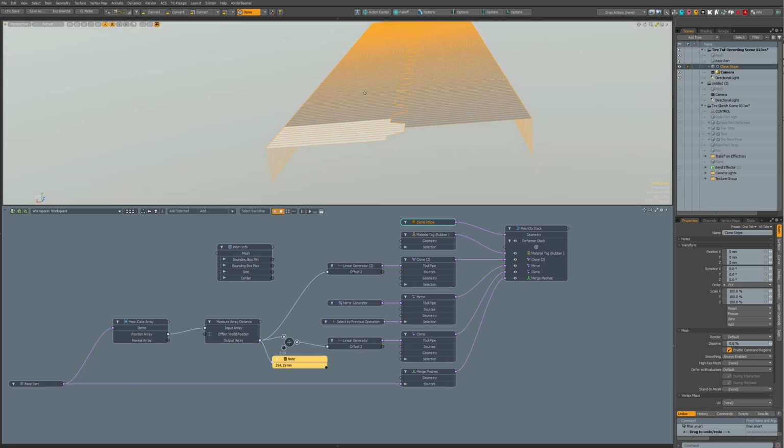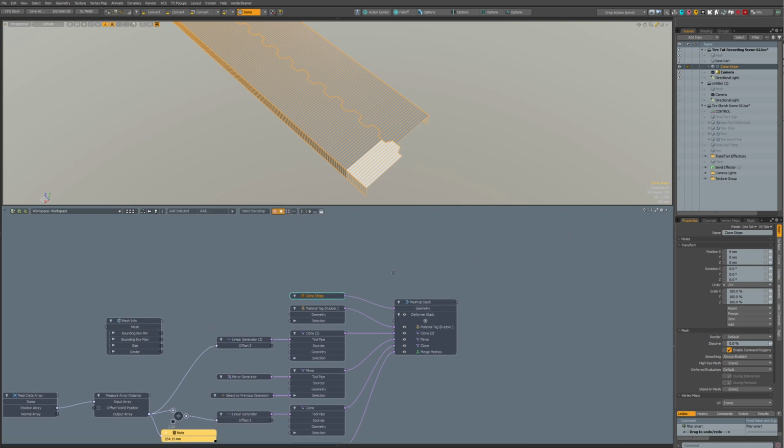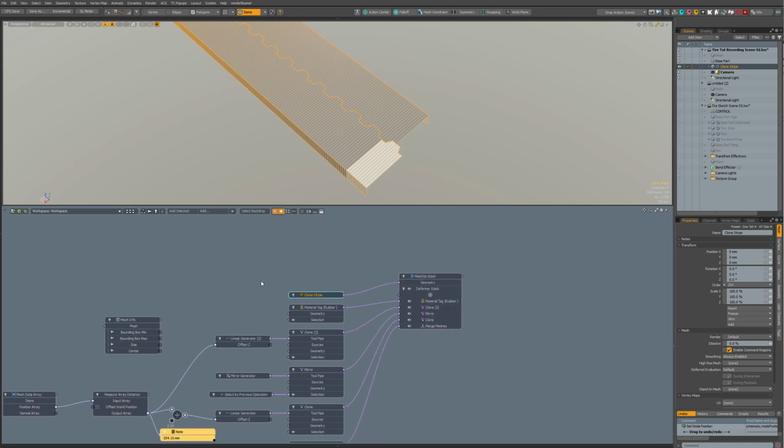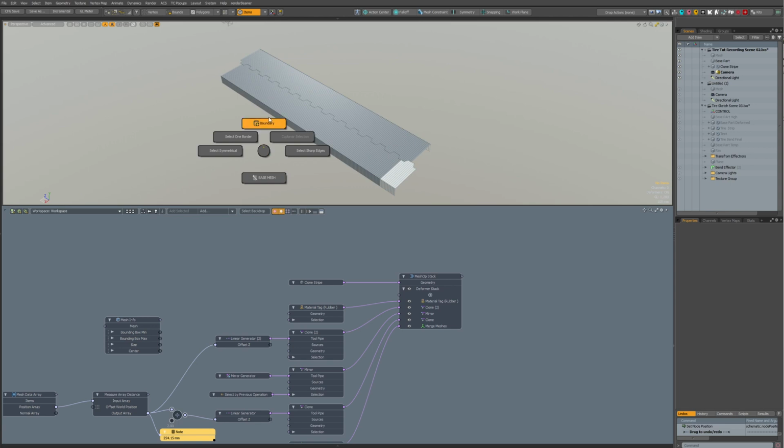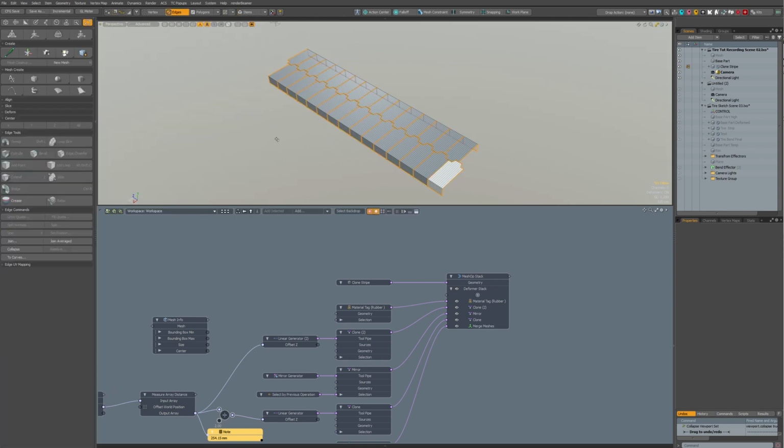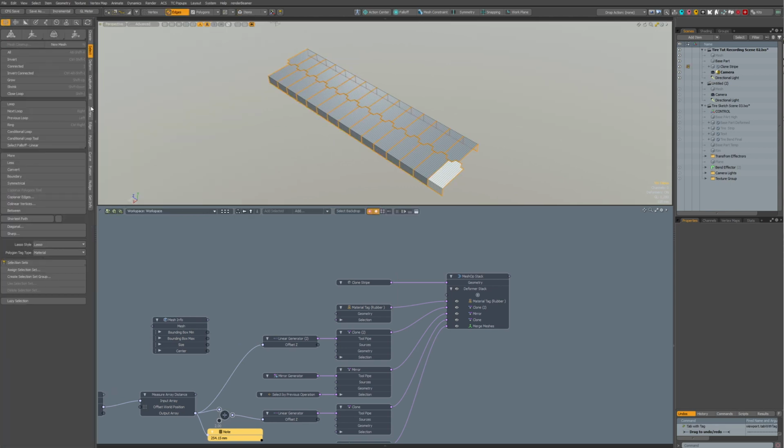So how does it look? It looks like it could work. So let's check. There's one way to check if a mesh is solid, which is to use select boundary. It's also in select. Here, select and boundary. I think it's that.